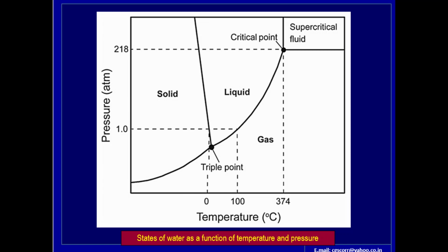And you can see a supercritical fluid, shortly called SCF, is any substance at a temperature and pressure above its critical point, where the distinct liquid and gas phases do not exist, but below the pressure required to compress it into solid. It can effuse through porous solids like a gas, overcoming the mass transfer limitations that slow liquid transport through such materials. So, supercritical fluids are superior to gases in their ability to dissolve materials like liquids or solids. Also, near the critical point, small changes in pressure or temperature result in large changes in density, allowing many properties of a supercritical fluid to be fine-tuned.